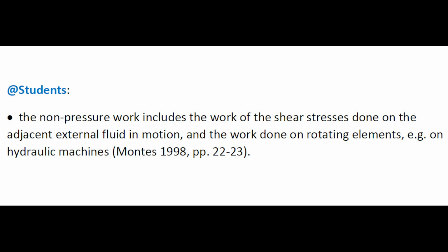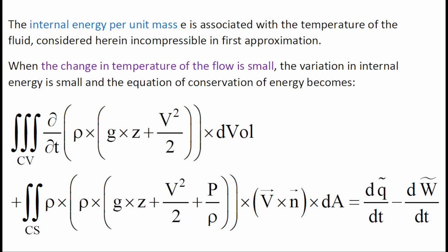Students, the non-pressure work includes the work of the shear stress done on the adjacent external fluid in motion, and the work done on rotating elements, for example on hydraulic machinery. The internal energy per unit mass is associated with the temperature of the fluid, considered incompressible here in first approximation.